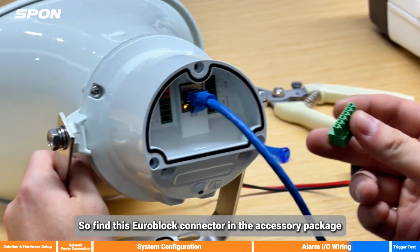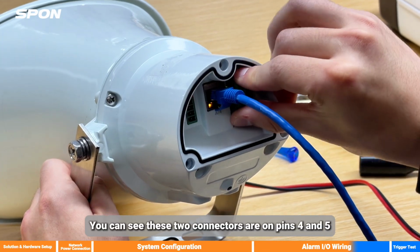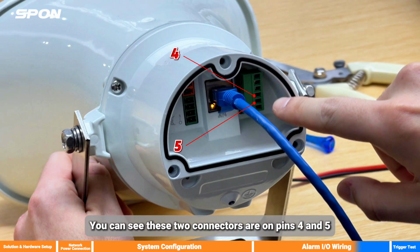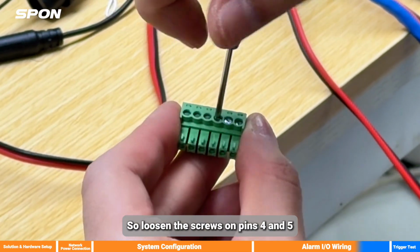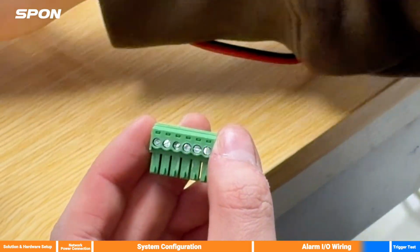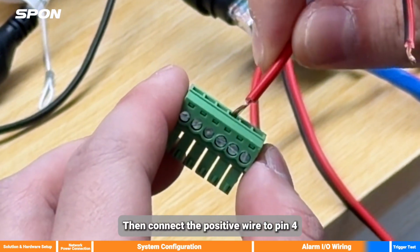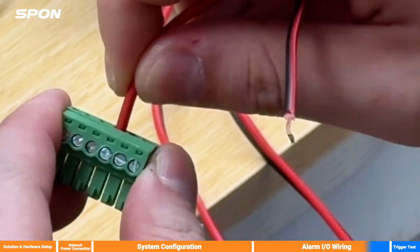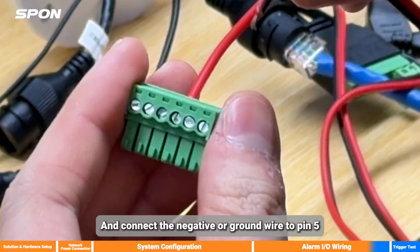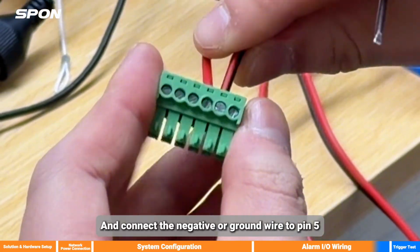Find this Euroblock in the accessory package, and you can see these two connectors are pin 4 and 5. Loosen the screws on pins 4 and 5. Then connect the positive side of the wire to this one, and the negative or ground side of the cable into the 5th one.